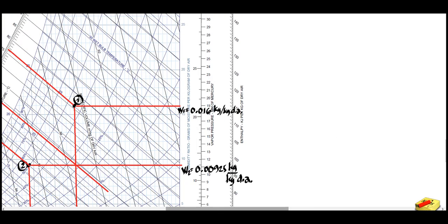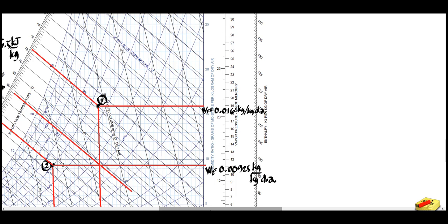So plotting in the curve, we have your humidity here. So this is now 15, this is 10, 11, and 12. So we have here 12. Humidity 3 will be 12, no? So this will be grams per kg of dry air, since what is written here is grams of moisture per kilograms of dry air. Okay.